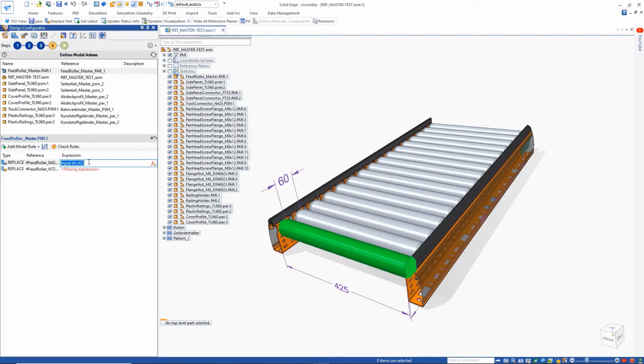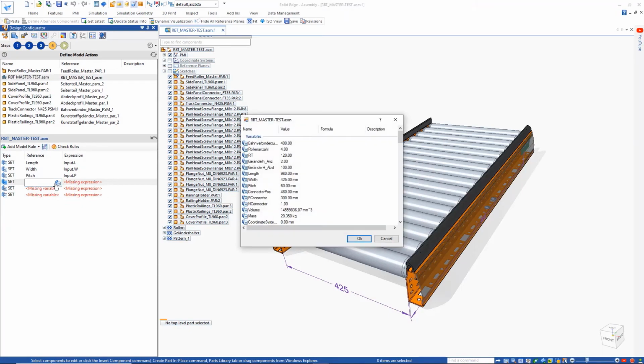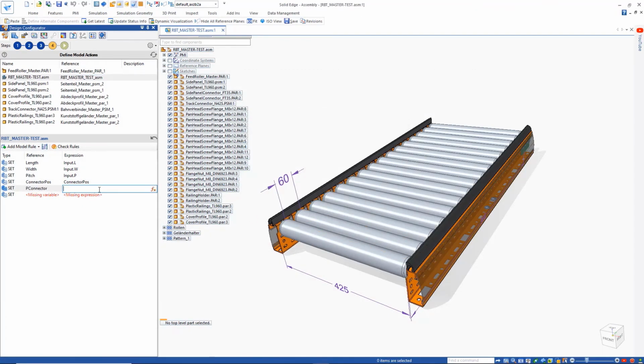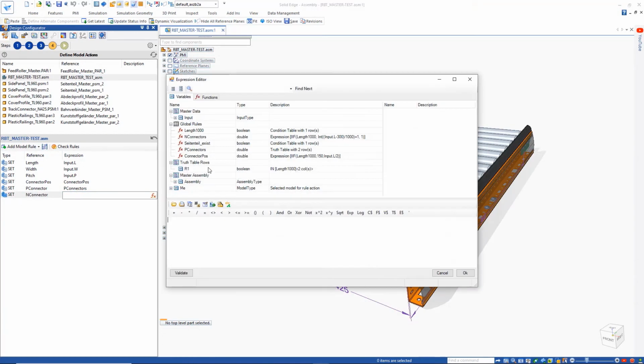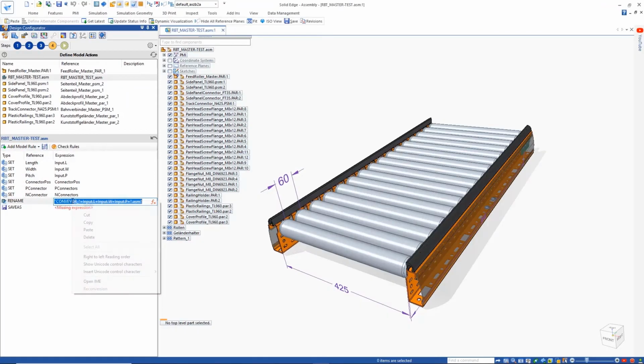This makes use of the standard alternate components function in Solid Edge to define the two replacement parts. We'll then set some variable rules connecting our model variables defined in Solid Edge to the functions we set up as global rules in the previous steps. A rename model action will ensure that our final assembly will be renamed appropriately, and also create the other necessary outputs, for example, step files as shown here. The order of these actions can also be easily changed.